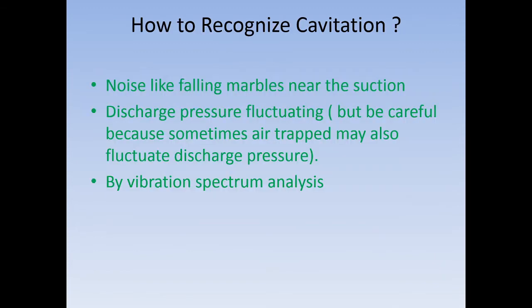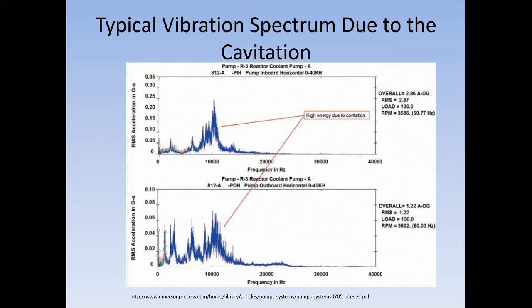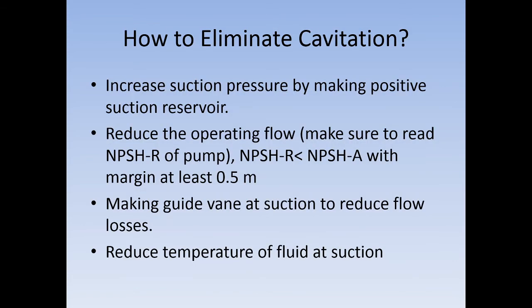Okay, so how to recognize it? As I said to you, noise like falling marbles, discharge pressure fluctuating, and vibration. By using vibration spectrum analysis, you can see that cavitation usually has typical symptoms of vibration. Like this vibration spectrum for cavitation, you can see there's a peak there. Usually there is a rule of thumb that if the spectrum is like this, it is highly possible because of cavitation.